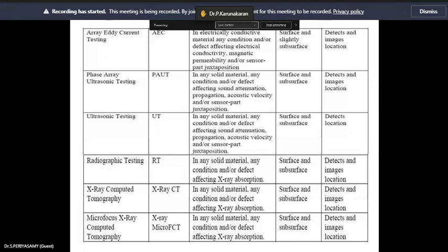Now the images are improved and you can get internal details. Then you can easily identify the particle size. So this will be magnified. For a square inch or a square mm, whatever image you capture will be magnified. In that image, you can count how many particles or how many pixels there are. Based on that, you can easily find the particle size. Even the porosity you can find. Here there's a part manufactured using a titanium, aluminum, vanadium based material.